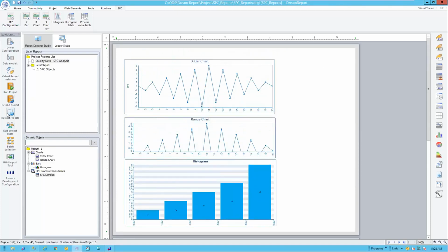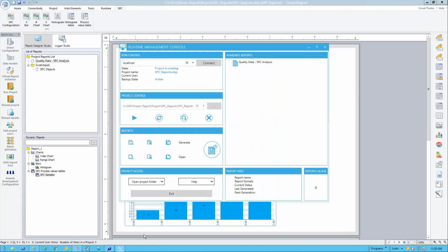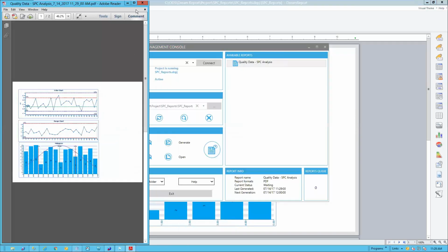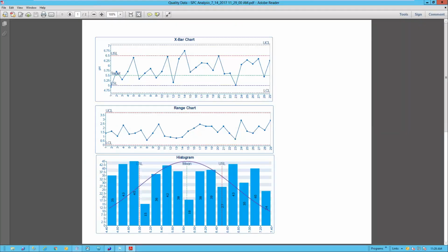Now if I wanted to run it, assuming I got all the parts and pieces in place right, this is my first attempt at the basic SPC table or report. Here we have it up, and let's generate this report. In this report, we have our sampling. We said the last 30 minutes. These are the samples taken once a minute. Here our target was in red. Looks like my range is off a little bit. My control limits in purple, my range of data, my histogram with distribution, my data actual distribution.